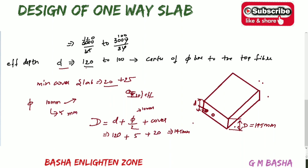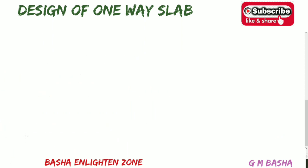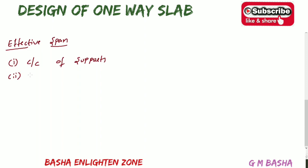Our next point is effective span. In the question they will mention the clear span, and based on the clear span we will solve the effective span. What are the conditions for the effective span? As I showed while explaining the beam concepts, the effective span is the center to center of supports, and the second point is clear span plus effective depth.